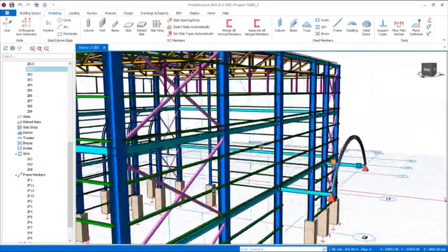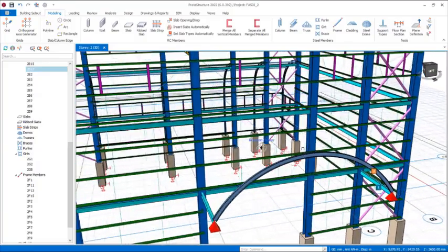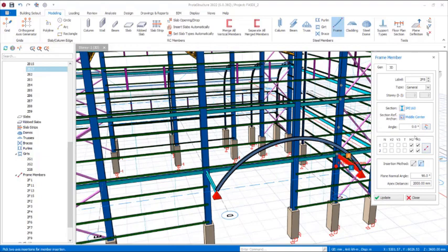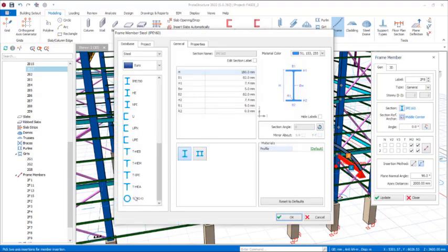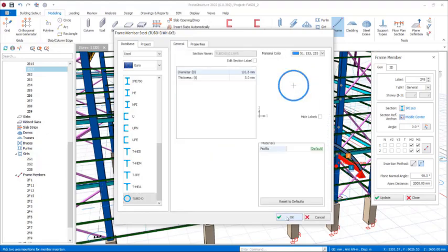So we are going to have a support pole that will be connecting this curved beam and then these stanchions. What we need to do is come over to the frame again, and in the frame provisions we will actually have to insert both sides of the pole. So we come to the section manager right there, and then we go to the tubular section right there, and then we navigate to the sections we've used: 101.6 by 5 millimeter thickness of the steel hollow sections, circular hollow sections. Select that and OK options.